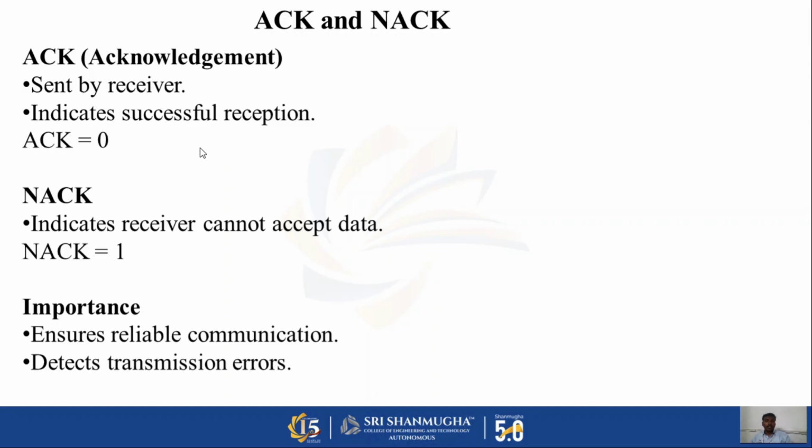It is represented by a logic 1. A not acknowledge may occur when the receiver is busy, when an error occurs, or when the master wants to terminate the communication. Acknowledge and not acknowledge signals improve reliability by ensuring that every transmitted byte is correctly received.